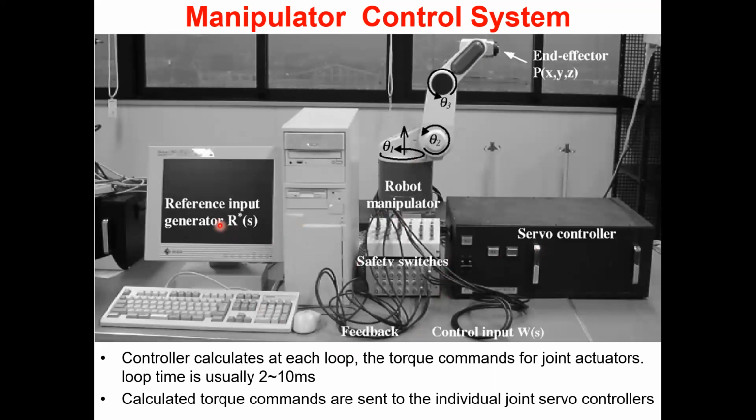So then what you do is you send this file, like a file input, to the servo controller, line by line, line by line. The first line, time 0, the second line, 10 milliseconds, third line, 20 milliseconds, like that. You send it according to the timer, okay? So once you send the first line, the servo controller latches these positions, theta 1, theta 2, theta 3, all references. Now this is a control system problem, right?